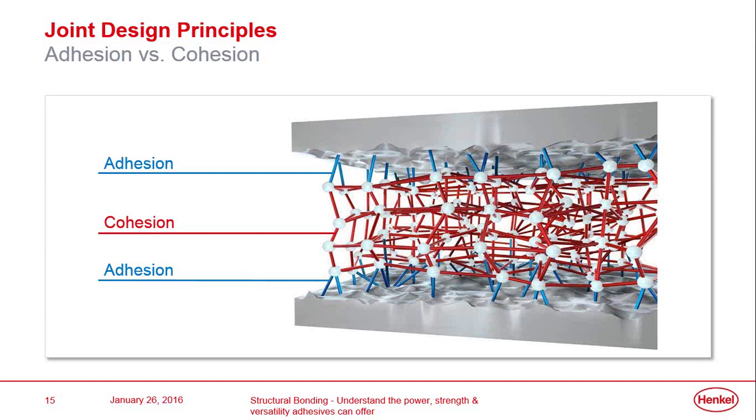Whereas if I take something a little different, like polyurethane here, you can see that I've got some degree of bend, but it's not hyper stretchy. It'll still carry a significant amount of load, okay? And therefore, with the red lines here, whilst there is some structure, there's not quite as much cross-link density, and therefore we have a slightly more flexible polymer. So it's a question of achieving good adhesion and having the right properties of the adhesive to give us the results that we're looking for.